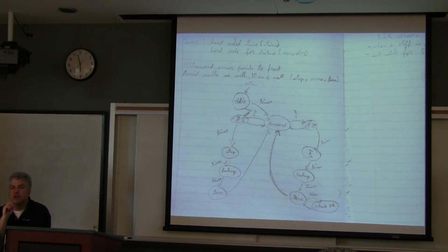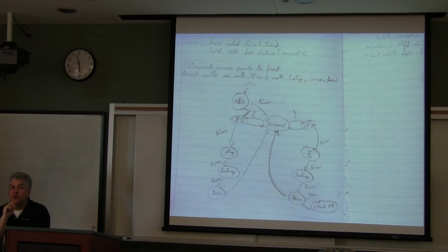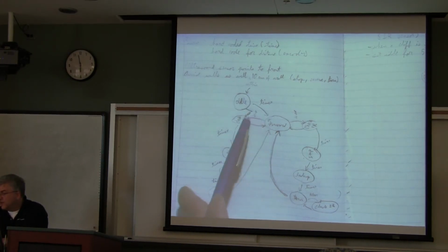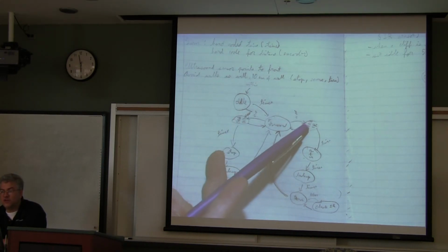Yeah, but you don't need that. Well, because he's got a loop going this way and this way. So are you checking it or is it going down? Or can you do both at the same time? No, it's like one's yes and then one's no. Now, one thing to point out in the state machine, you can only be in one state at a time. So at that point, while he's checking the ultrasound, he's totally ignoring the infrared.